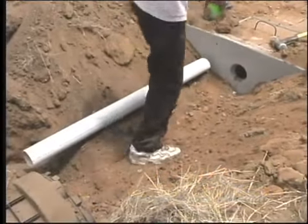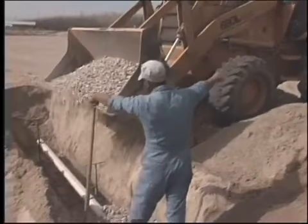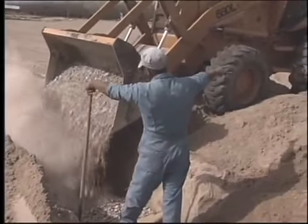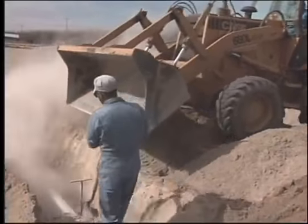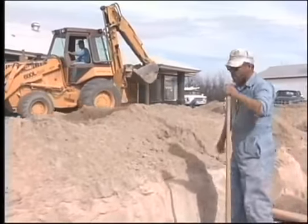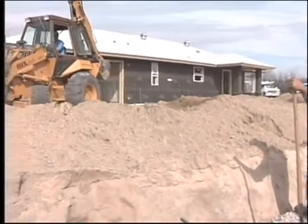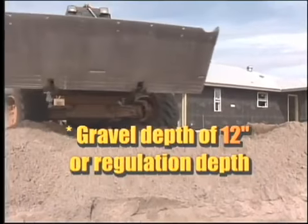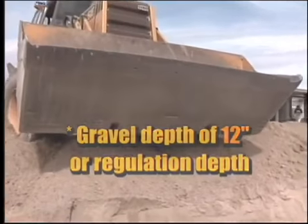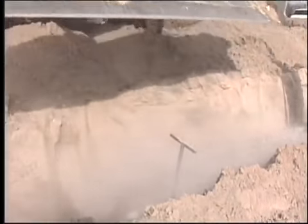Once the trench is done, it is time to place the distribution system. Until recently, the use of gravel and pipe for a drain field was very common. Use washed gravel ranging in size from 3/4 inch to 2 1/2 inches, or other trench fill material that has been approved by regulators. Carefully place the gravel over the bottom of the trench to a depth of 12 inches or regulation depth. The gravel must be completely free of fine material, clay, and silt, or this fine material may plug the soil at the bottom of the trench.